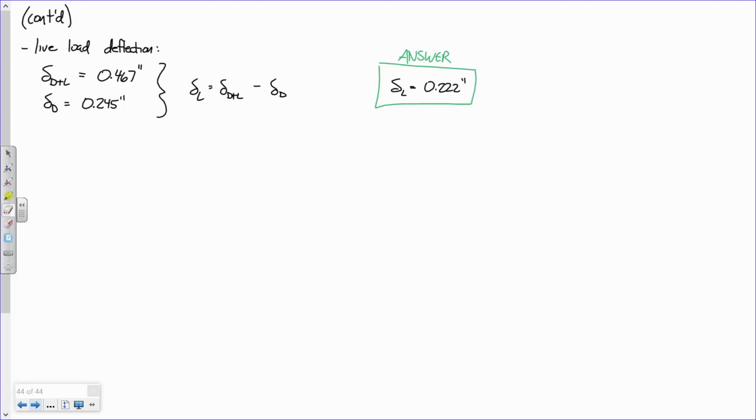And usually in concrete land, we'll just prop the formwork up a little bit. In steel land, we will actually bend the beam upwards, feed it through a horizontal machine, cold bend it to where it's actually curved upward a little bit. We can take care of that in concrete design through just propping the forms up. But if we're talking 1/4 of an inch over a beam that's 20 foot long, it would probably be conventional to ignore it. That's a good question. So it just depends on your magnitudes.